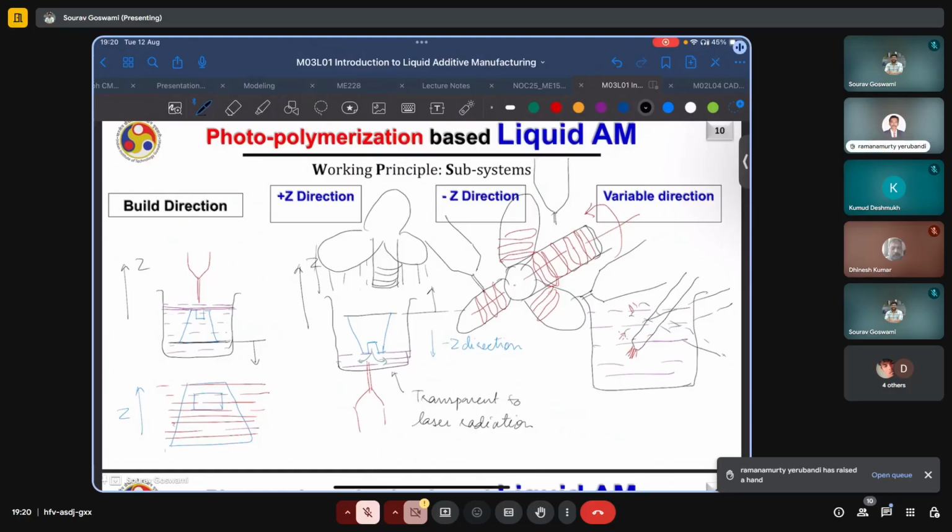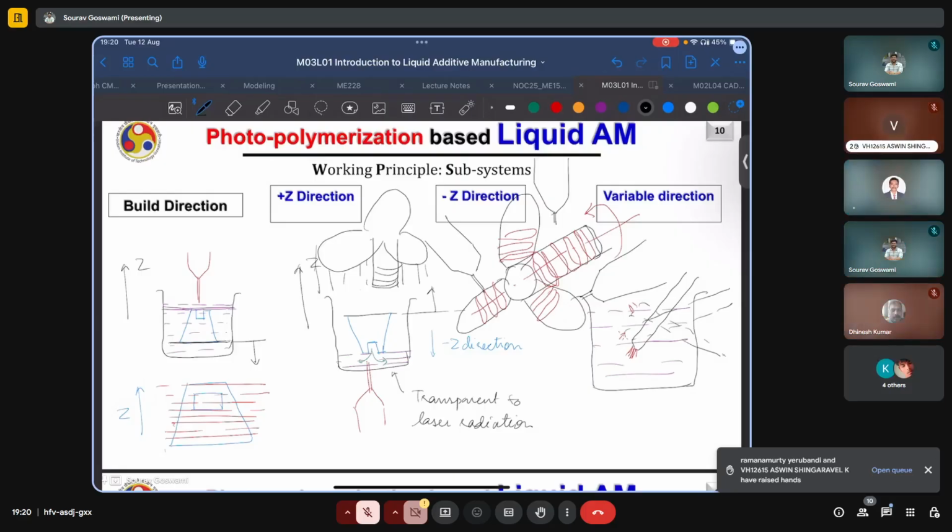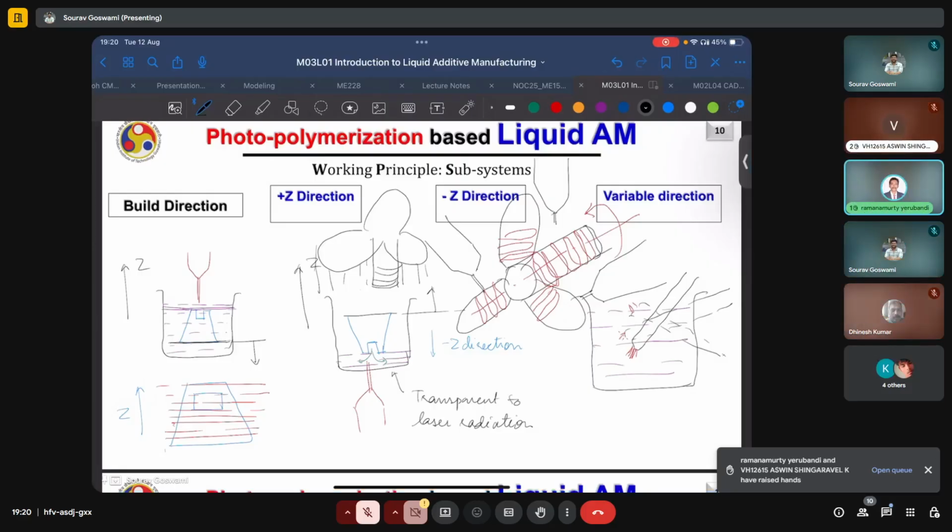It's difficult to say. I think it will, but I should not comment on it without carrying out any such experiments. But the microstructure will change. I have seen some examples where it changed, and microstructure dictates strength locally at least. So locally, of course, you will see a lot of variation. Say if you do a hardness mapping or elastic modulus mapping, you will see changes locally. But whether that will affect the bulk strength as a whole is a more complicated answer. Okay, thank you.